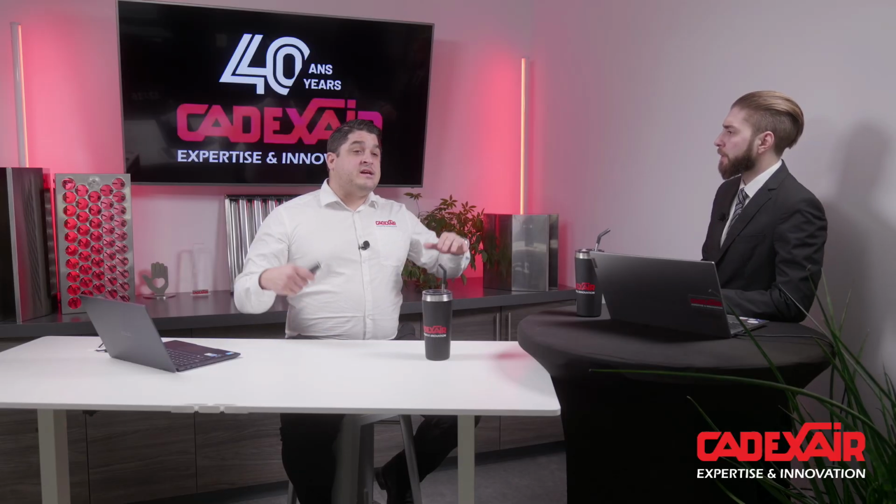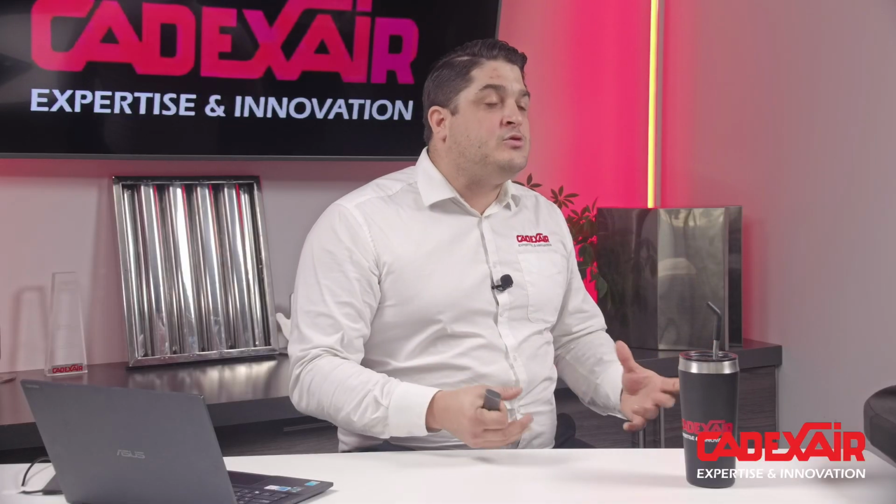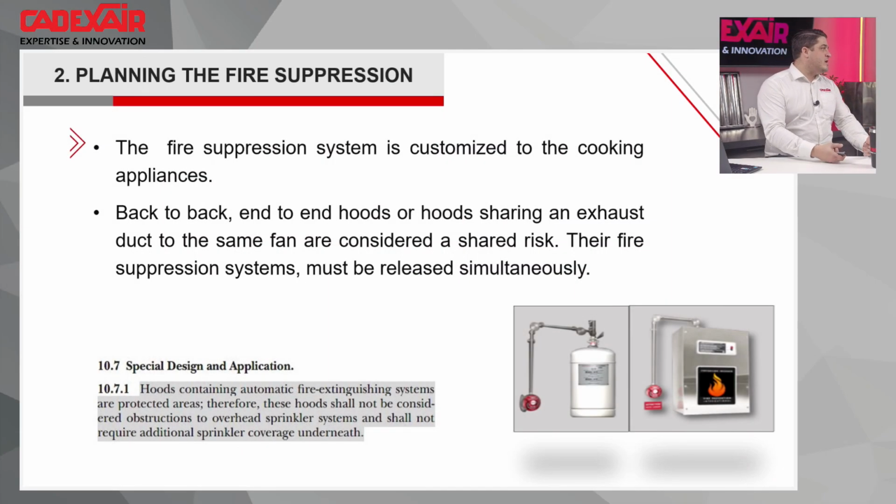Do you have a sprinkler in your building? Yeah, we have water sprinklers. Perfect. So a kitchen exhaust hood type 1 is considered a covered space. So you don't have to put any water sprinkler in that case, because it's already protected with the fire protection system of the hood.